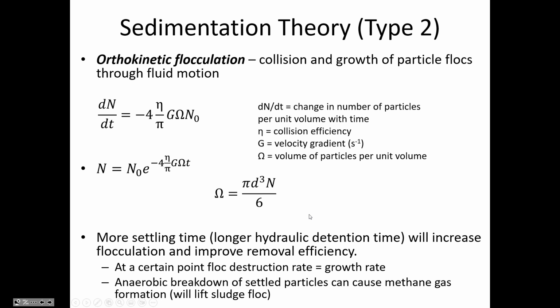And that can cause the formation of gas bubbles, which, when they're formed at the bottom of the clarifier, begin to rise upward and suspend the particles that are trying to settle down. Those little gas bubbles, as they go up, will cause the flocculating particles to float rather than to settle. So that's why we don't try to have the settling basin operate for 12 or 18 or 24 hours, because the performance just wouldn't keep improving. There's kind of a threshold limit.